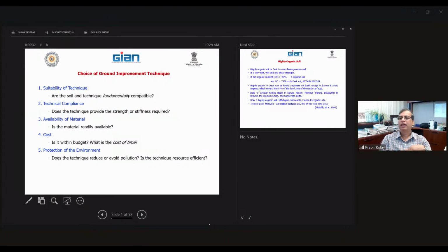Compactor and vibrator. And then also for the shallow depth, then we talked about dynamic compaction or controlled blasting for the deeper depth. And then compaction, all these different compaction methods. Then we talked about the hydraulic modification, getting rid of the water, and then the surcharge load, preloading, and also when you accelerate the consolidation. Yesterday we talked about sand drain. We talked about prefabricated sand drain, and then PVD drain. We talked about that, and then the chemical modification. And yesterday we talked about the different chemical admixtures you need to use.